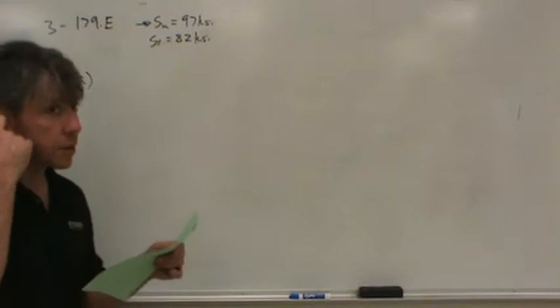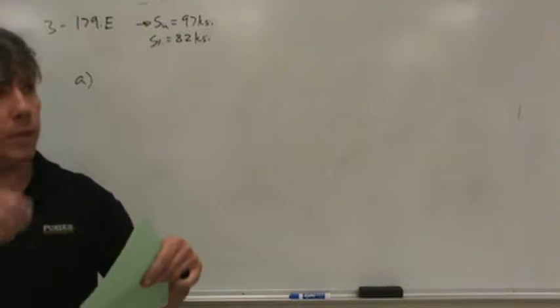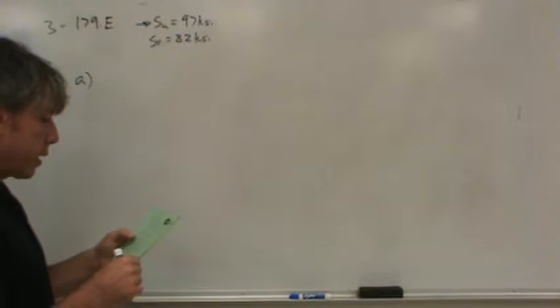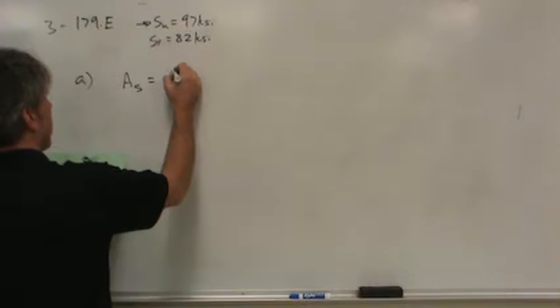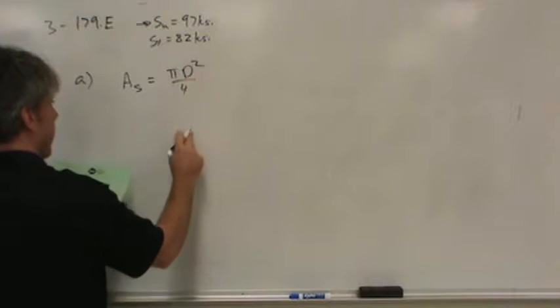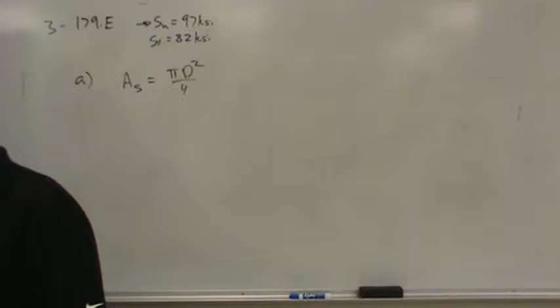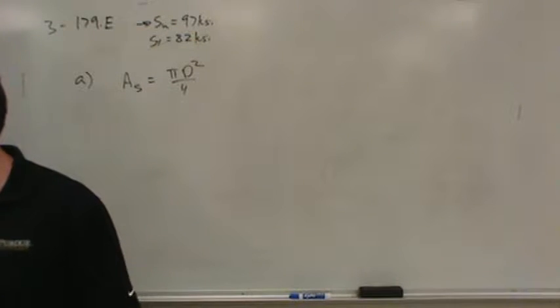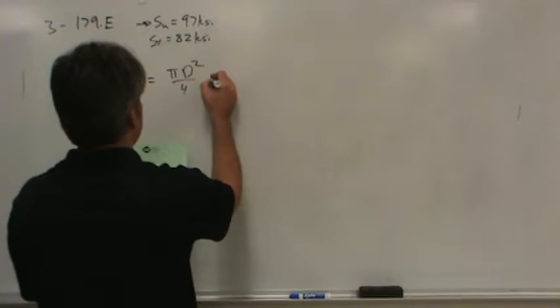We're supposed to analyze pin shear. So if you look at the figure, you can see as the link plates pull on the pin, they could shear the pin. All right, so the area available for shear is pi d squared over 4. I was thinking I may have made another mistake because the pin does go all the way through a link. But there's nothing on the outside of the pins holding it, so only the inside area would shear. So this analysis should be sound.